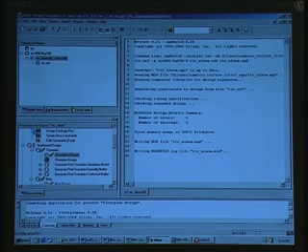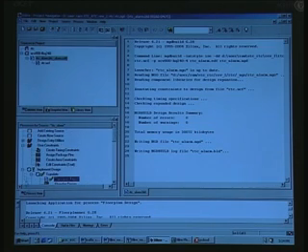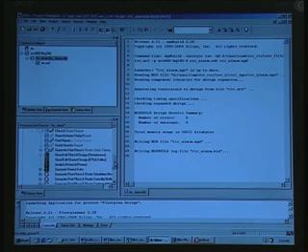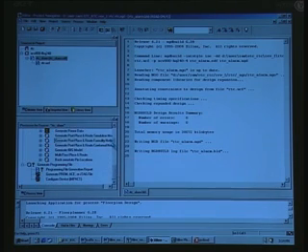And another window is processes for source, and here what is listed is implement design and map, place and route, all this. There are wide varieties of place and route, we will see one after another, and then finally to generate a bit file we need to generate programming file.